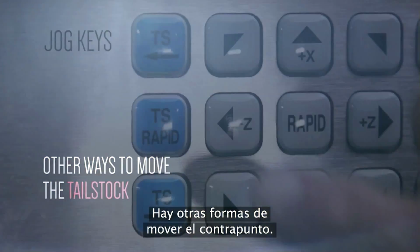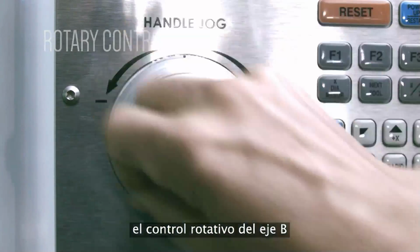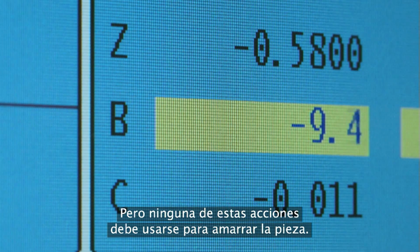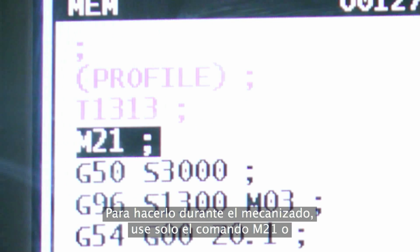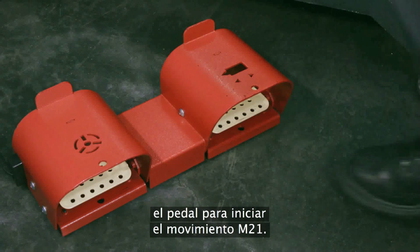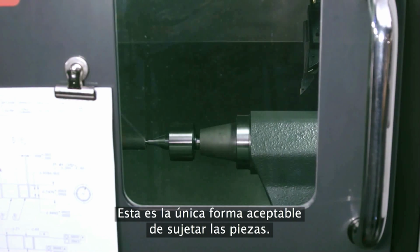And there are several other ways to move the tailstock. You can use the tailstock jog keys, handle jog the B-axis, or command a B-axis move. But none of these should ever be used to clamp the part. To clamp your part during machining, use only the M21 command, or the foot pedal to initiate the M21 move. This is the only acceptable way to clamp your part.